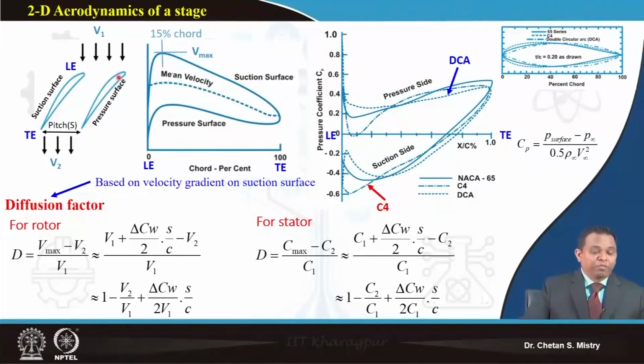So, here we have arranged our two aerofoils at a particular section, say at mid section. If I arrange them in this way, that is called a linear cascade. We will discuss the meaning of that. At this moment, just realize I have arranged these two aerofoils as per my section at a particular station. This region, as we have discussed, is my leading edge and trailing edge. We have inlet area and outlet area. Suppose my entry velocity is V1, I will have my exit velocity V2. The distance between these two aerofoils or blades is defined as the pitch. If I measure the distance from leading edge to trailing edge, that is defined as the chord, and if I measure the distance axially, that is called the axial chord. We will discuss again when we discuss the aerodynamics of these blades.